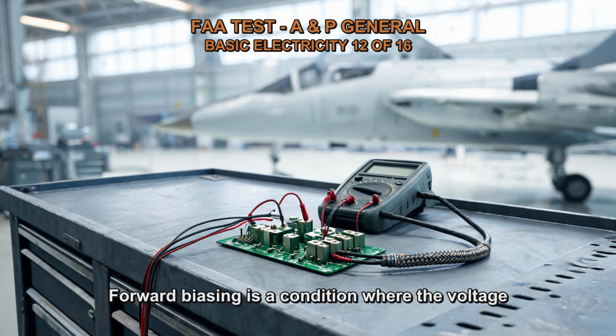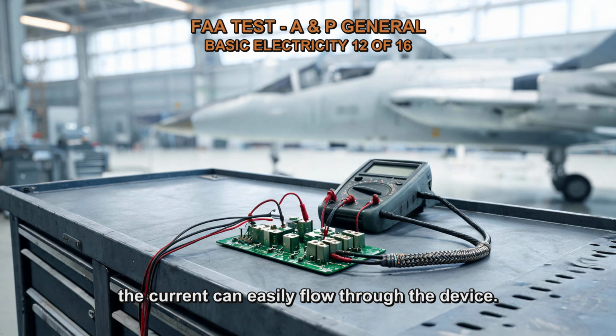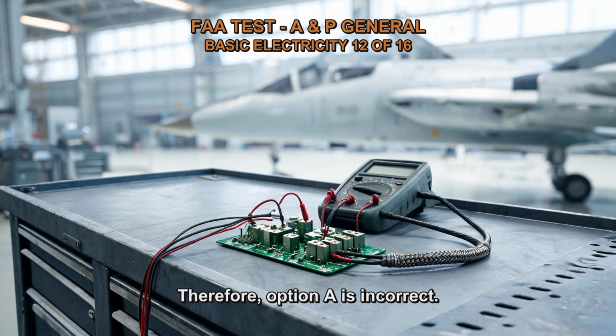Forward biasing is a condition where the voltage applied to a solid-state device is such that the current can easily flow through the device. In this condition, the device conducts and allows the flow of current through it. This is in contrast to reverse biasing, where the device does not conduct. Zener breakdown occurs when a Zener diode is reverse biased and it conducts due to the breakdown voltage being exceeded. Therefore, option A is incorrect. Option C is also incorrect, as turning off occurs when the device is not biased or when the voltage applied is less than the threshold voltage.